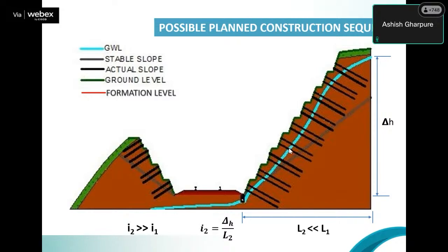I would like to highlight that a toe wall is not a retaining structure, not an earth-retaining structure. It is not actually taking care of the whole hill load. If the active pressure of the hill comes, then the toe wall will be thrown away. But the toe wall is necessary to keep this exit gradient in check. And that's the important part the toe wall does, apart from giving some confinement at the toe, right? So this is one aspect everyone should keep in mind, that a toe wall is almost a must in any hill cut slope, apart from maybe some rocky areas. Next, please.